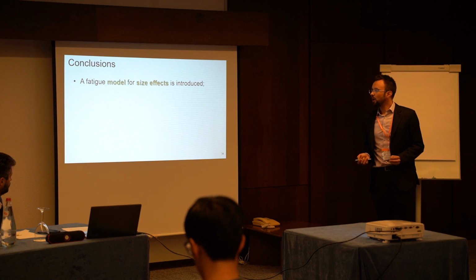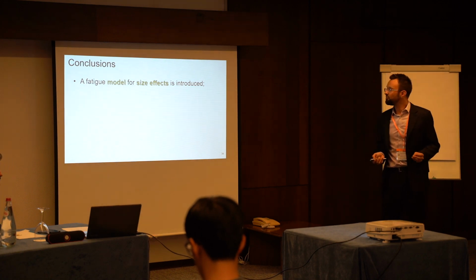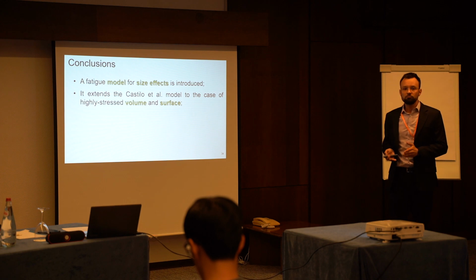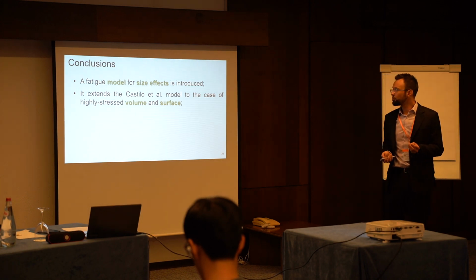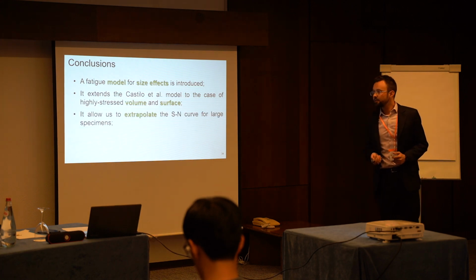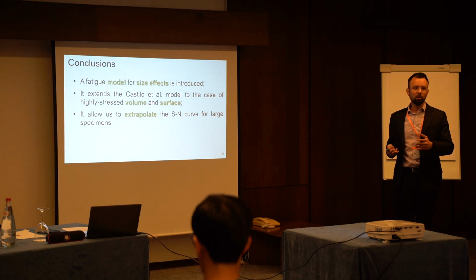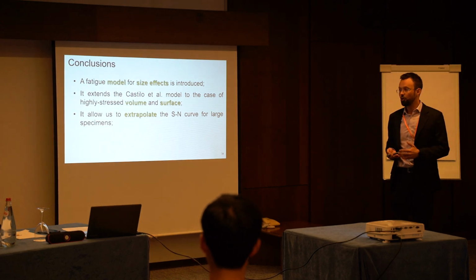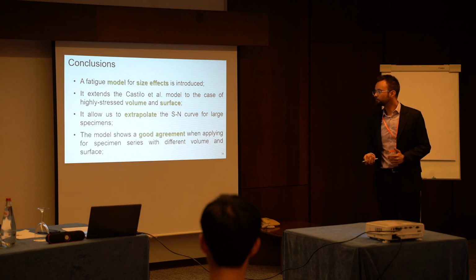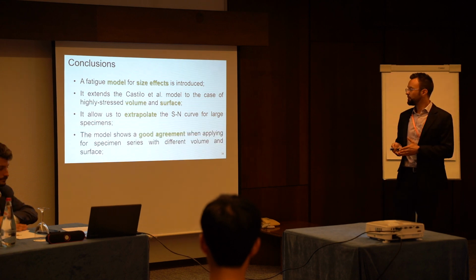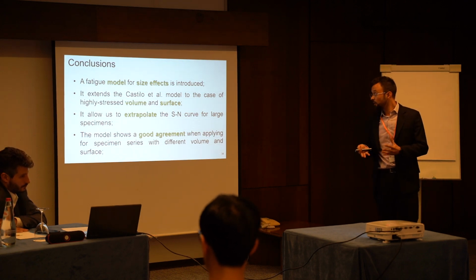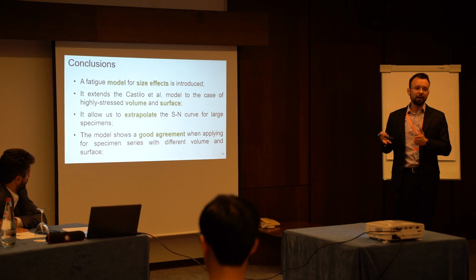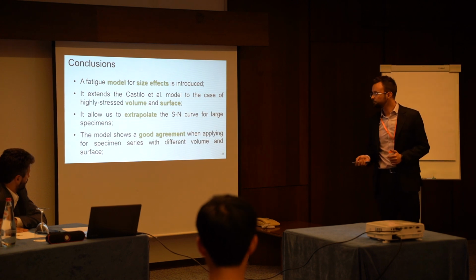So we introduce a fatigue model for size effects, and this model extends the general Castillo model to the case of high stress volume and also surface. It allows us to extrapolate the SN curve for large specimens, and the model shows a good agreement when applied to our experimental data of specimen series with different volume and surface.